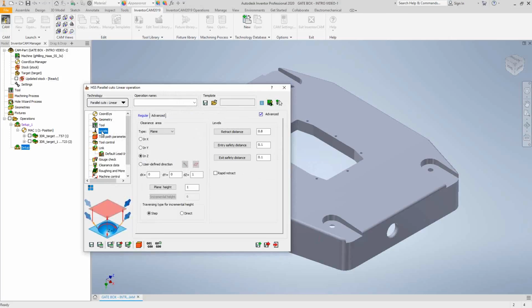Now, what's unique about HSS is you can choose any shape of tool, shape tools, or the standard definition tools as well. And I mentioned earlier, undercutting. This is the only toolpath that can do undercutting. It's all based off of the shape of the tool. So it's maintaining that tangent point with whatever cutting surface you've defined on your tool with the surface you selected in your geometry section.